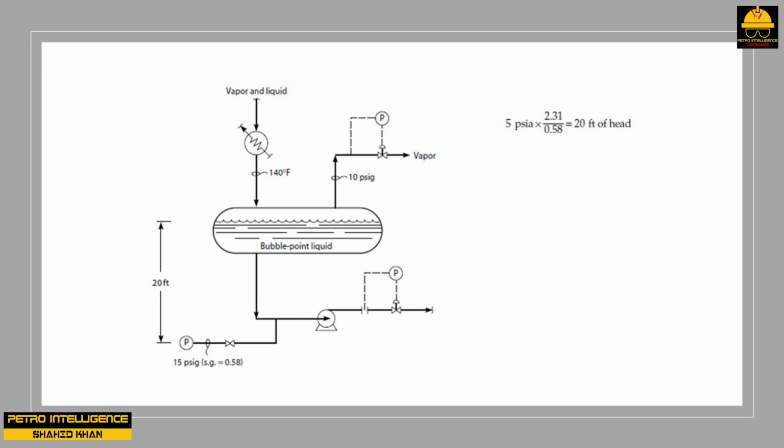Let's try one more time. Suppose we tear off the insulation on the suction line and on the pump case and then spray cool water on the bare line. The temperature of the liquid in the drum, which is at 140 degrees Fahrenheit, cools as it flows into the pump. By the time the liquid reaches the eye of impeller, it is cooled to 135 degrees Fahrenheit. Will this slightly colder liquid provide more NPSH to the pump? Answer is yes. But why?